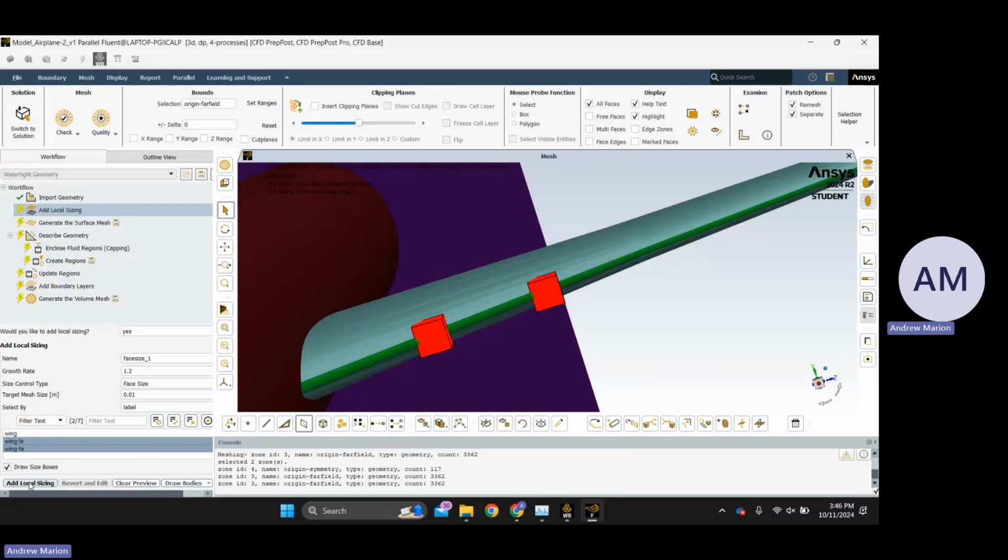And then when you get to the results phase, you can plot just on the fuselage. If you want to see results just on the wing or just on the fuselage, you need to name it beforehand, or you won't be able to divide it properly. The naming is the last step in the geometry process. You can also do it in the meshing process if you want, but it's usually easy to do in the geometry. When you import it over to meshing, if you forgot to do it, you can still name it here, but name it before you mesh.